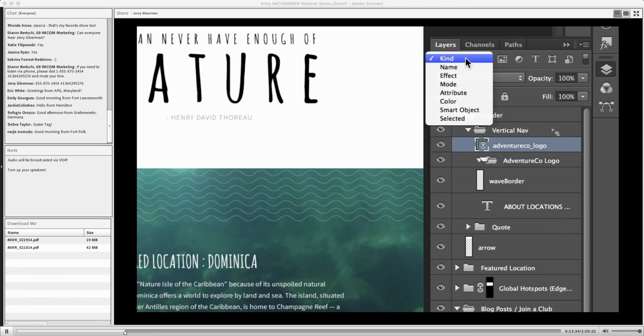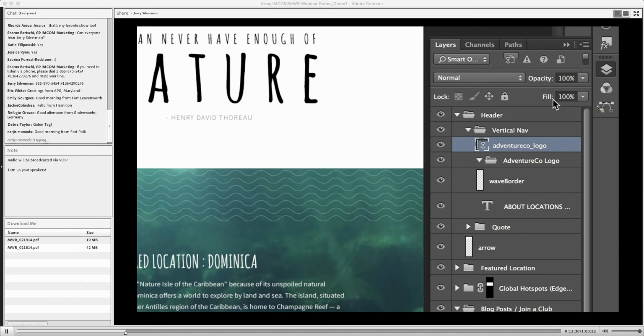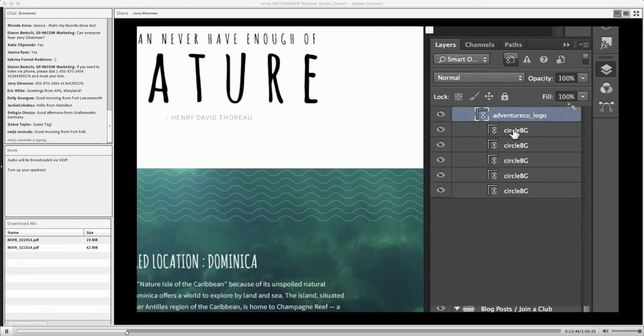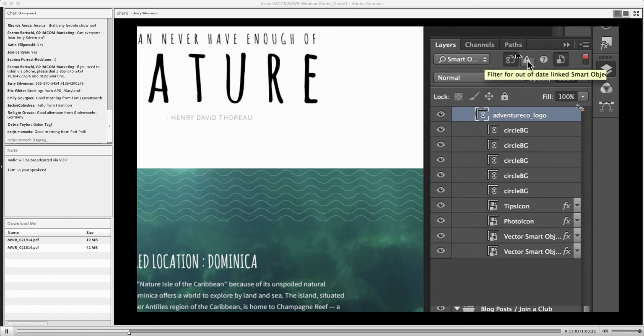So I'm going to look for all the smart objects in my document. Let me see, right? So I'm going to look for only the linked smart objects. So there's the linked smart objects. I'm going to look for the embedded smart objects. So you can do basically both, have linked or embedded. If there are any with missing or erroneous linkages, then you can find those as well.